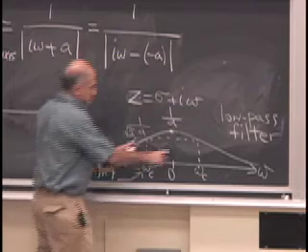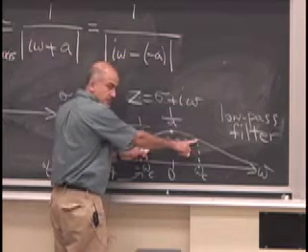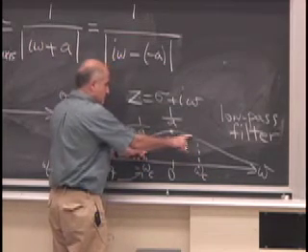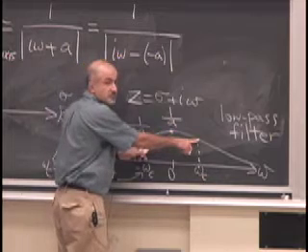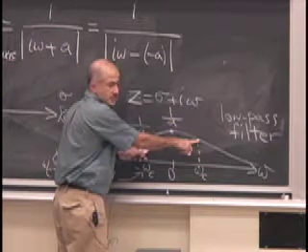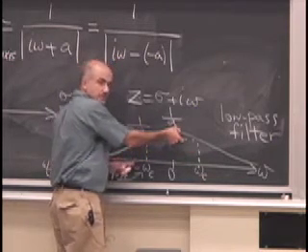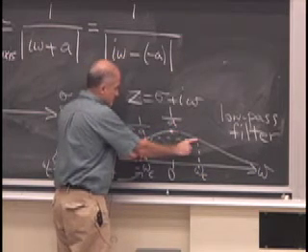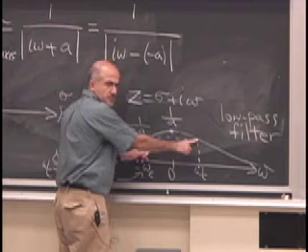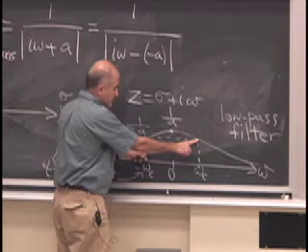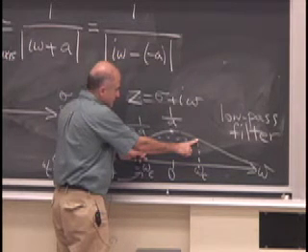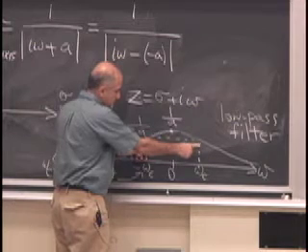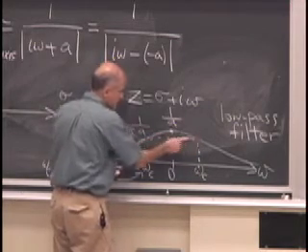So basically what they're saying is, yes, we know that this frequency response is not exactly flat over this range. But we can tolerate this much degradation, but cannot tolerate anything more than that. So a rule of thumb, it's a heuristic, there's no objective reason for this, is that they consider the bandwidth of the filter to be this range of frequencies.